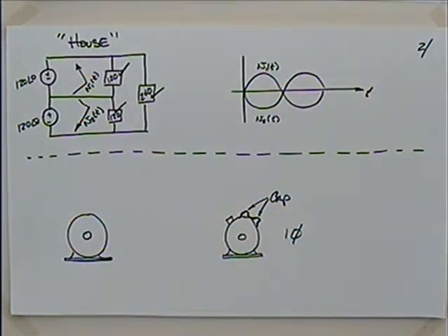Okay. Now, you can have different types of motors. You can have single-phase motors without those, but when we talk about motors that have a lot of torque and we're going to put on an air compressor or a table saw or something with a single-phase system, they're going to have those capacitors. Whereas a three-phase motor doesn't have those. So that's one real easy way to tell them apart.